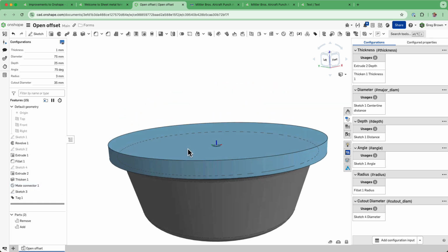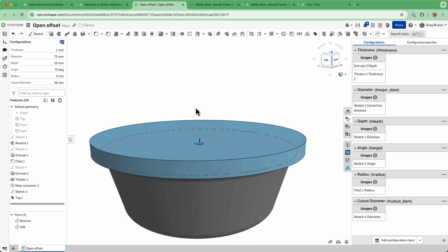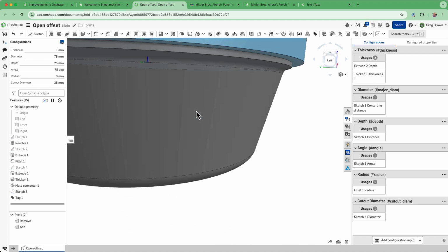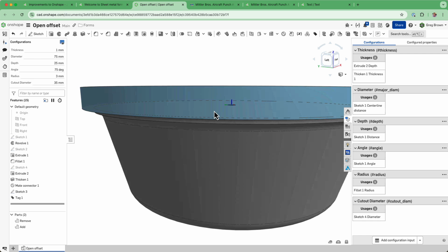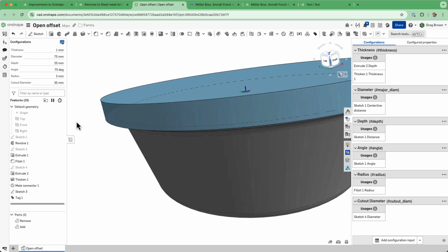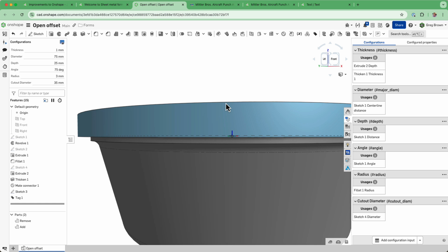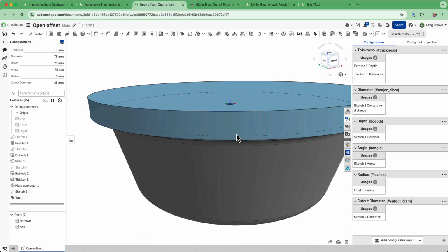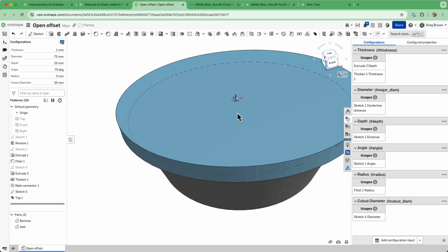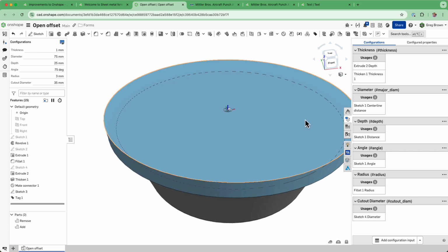Now, if you model everything carefully at the origin, like I have here, I've modeled everything at the origin, so where this thing would line up and be applied to the sheet metal model is the origin, and it will assume that. But if you want to put it somewhere else, you can create a mate connector and choose that in the tag.